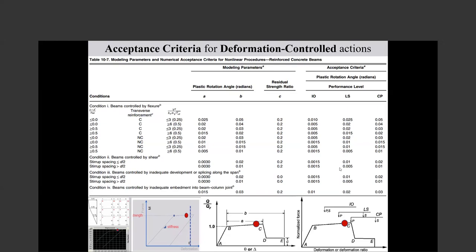And many of the damages in, like, the Chile earthquakes and Turkey earthquakes, places that have concrete shear walls, the long, tall shear walls, were due to this phenomenon, and because of that, they generally limit the amount of axial force due to the earthquake in this shear wall. For example, 0.35.